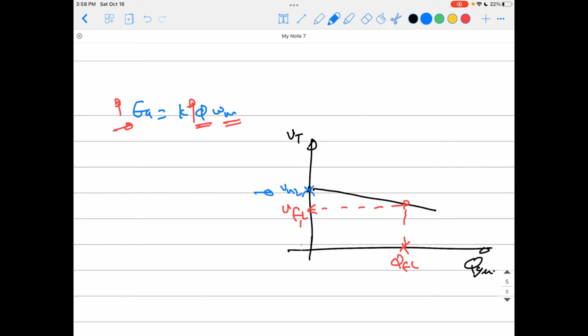If you want to restore this value back, because we now need the voltage to go back up to this point, what will happen is we will increase the excitation. We will push the field up by increasing the excitation, and this will increase the induced EMF. Increasing this, we are now working on a different curve, which is this curve. So increasing the excitation like this will change to this one now. Seeing here, at the same Q full load, you get back to the value of the voltage which was no load at first. So this becomes your V full load 2 after increasing the excitation.